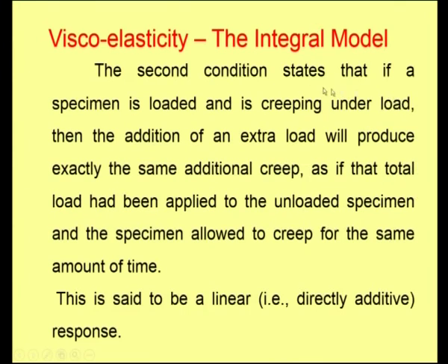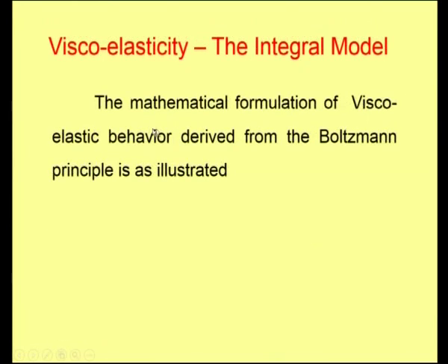The second condition is that if a specimen is loaded and is creeping under load, then the addition of extra load will produce exactly the same additional creep as if the total load had been applied to the unloaded specimen and the specimen allowed to creep for the same amount of time. This is said to be linear, that is, a directly additive response. We will see that the mathematical formulation of viscoelastic behavior derived from the Boltzmann principle is as illustrated here.